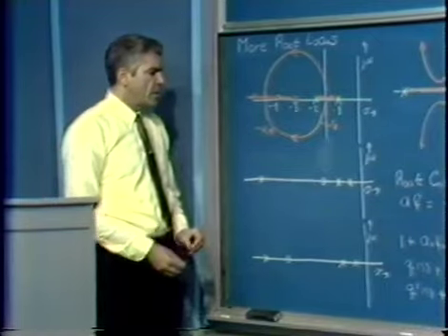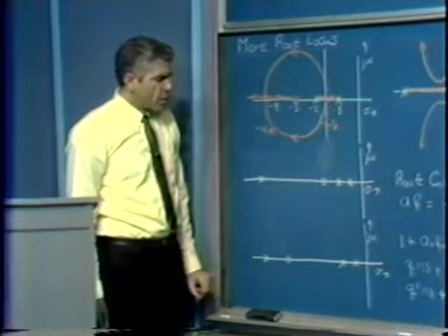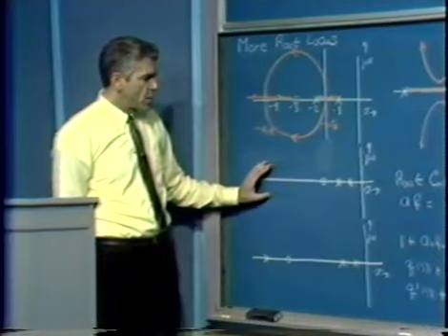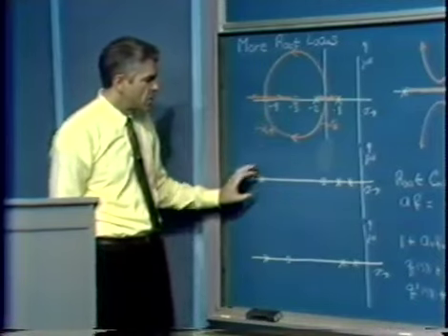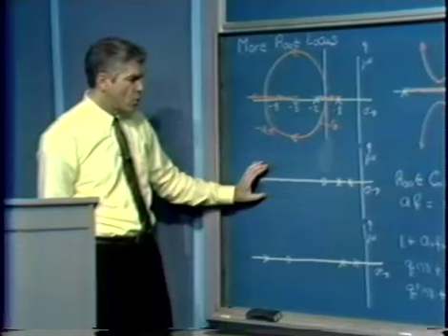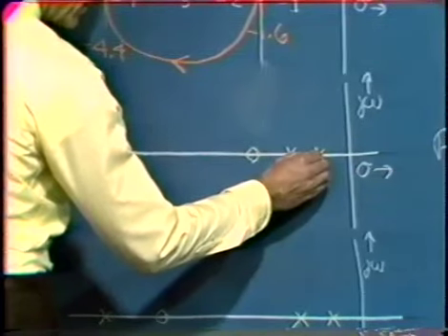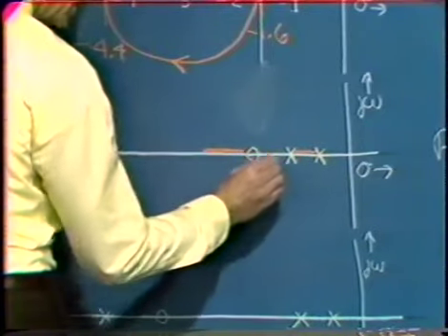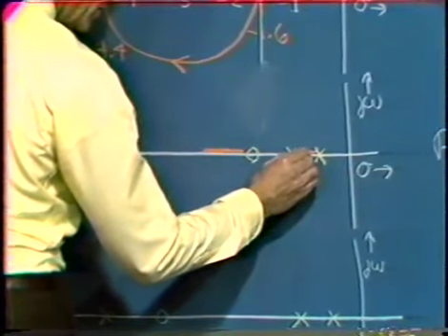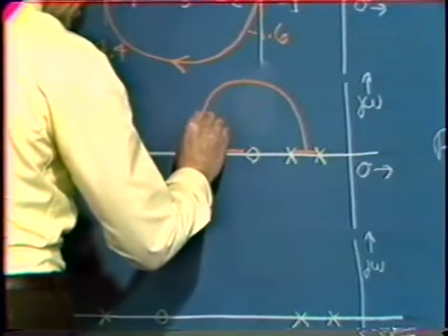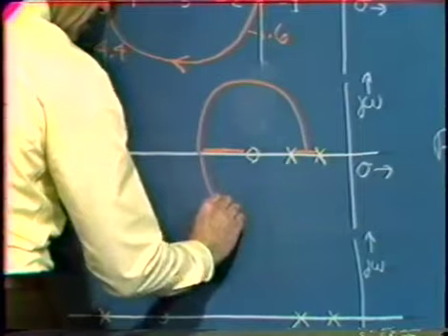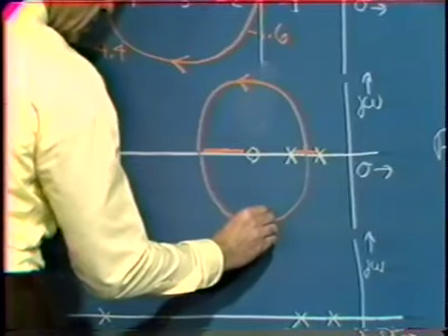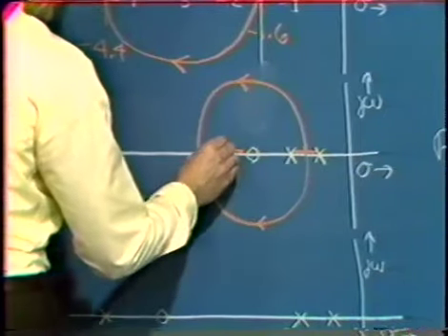We could determine the root locus initially by ignoring the remote pole, and under those conditions, we get a root locus picture very much like we had above. So we'd conclude that to the extent we were able to ignore the third pole, our root locus diagram for this situation would look something like so, and a circle between these 2 points, with the arrows indicating the direction of increasing A0, F0.